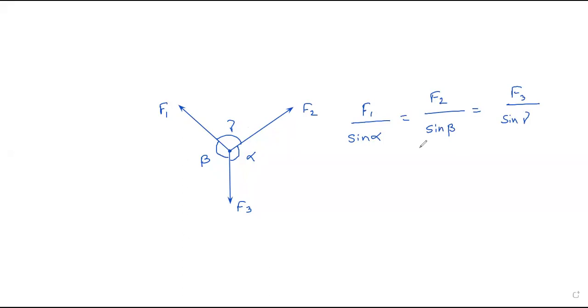So what are the points I have told you? You should remember those points, and those are the limitations of Lami's theorem. First, you cannot apply this theorem when two forces or four forces are there. Only for three forces can you apply Lami's theorem. If a fourth force is involved, you cannot solve by using Lami's theorem. You have to use summation Fx and summation Fy if more than three forces are there. That is the first thing.